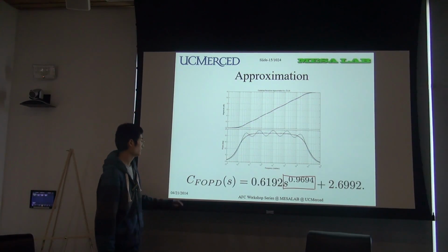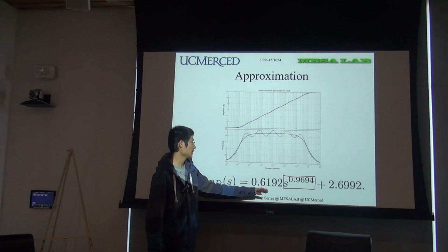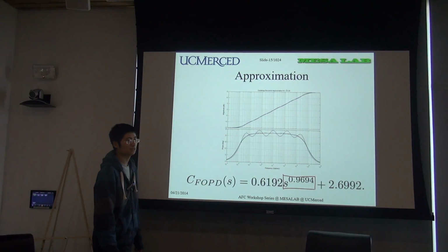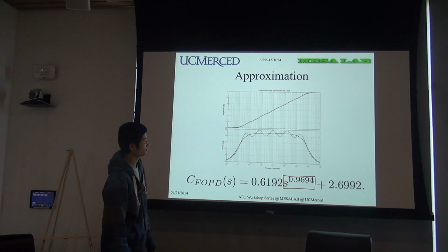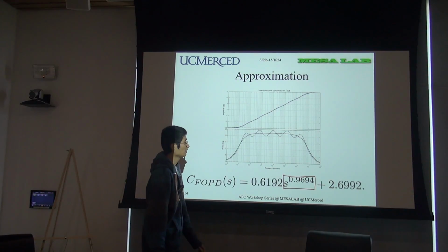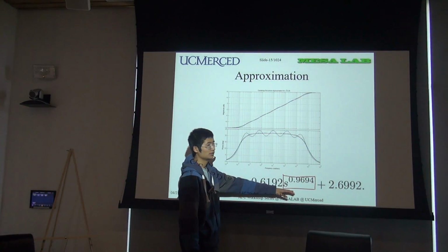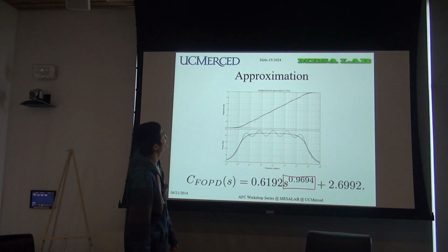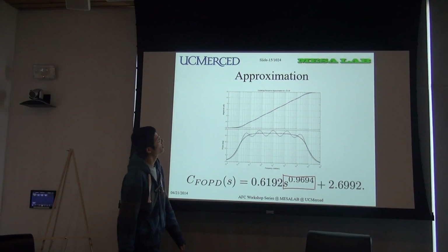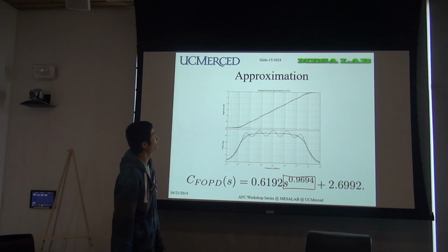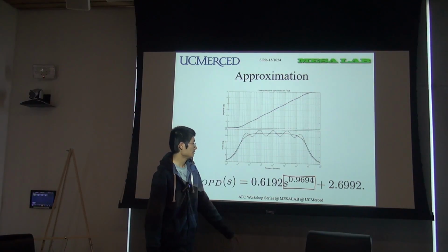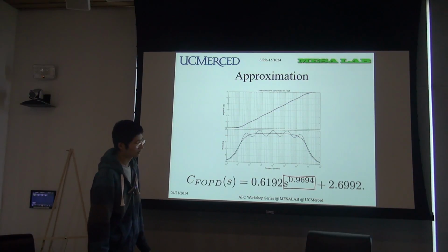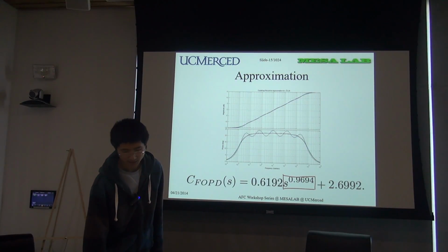After we got the calculated fractional order PID controller transfer function, we have to implement that controller in the practical system. Then we should convert this into something we can implement. We use the Oustaloup approximation method to convert this to a high-order integral order transfer function. In this way, we can implement that.